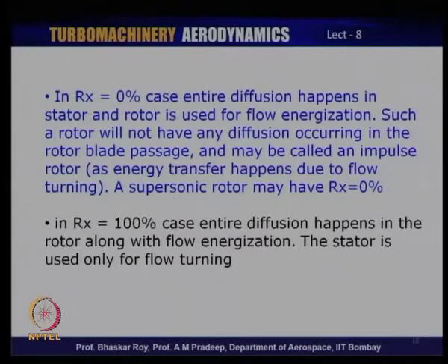Hence, such a blade may be called an impulse rotor, very similar to the impulse turbine that you may have heard of. We shall be doing it in the turbine chapter later on, and hence the energy transfer happens due to the turning of the flow. So, the turning of the flow essentially is responsible for the amount of energy transfer, and no diffusion is occurring in that particular rotor in which the degree of reaction is set as 0.